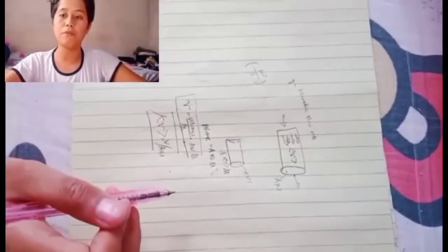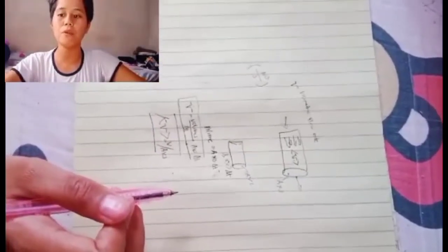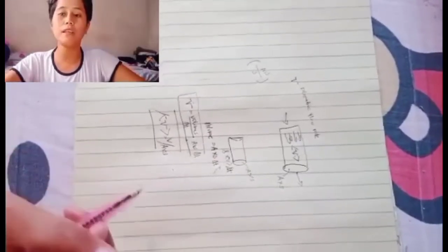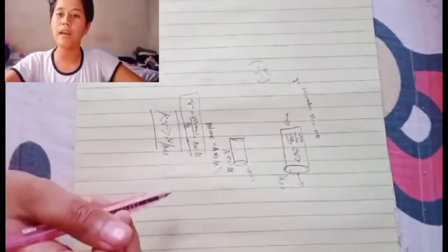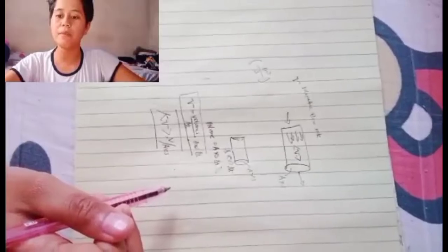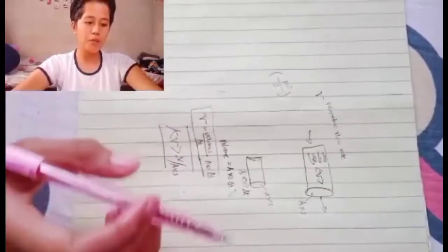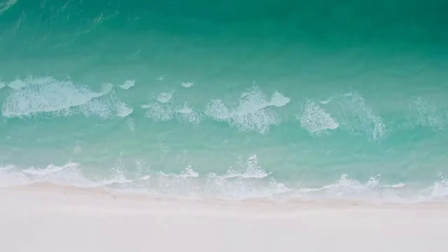That's a really useful relationship for steady turbulent flow, because we are often able to measure the volumetric flow rate. We know the cross-sectional area that it flows through, so we get the average velocity. Again, this is limited to steady turbulent flow, but that is a very common circumstance in engineering practice.